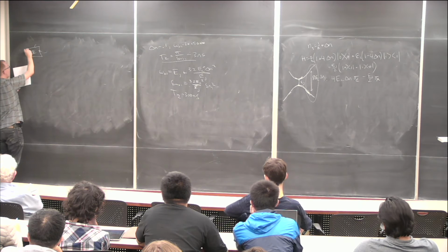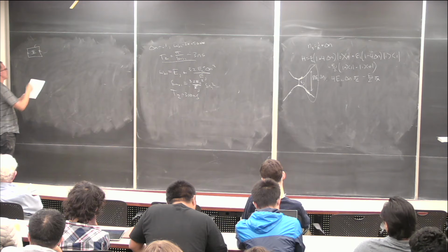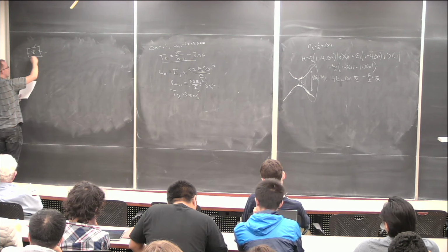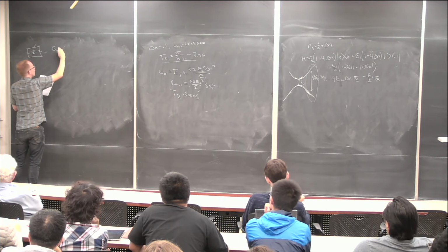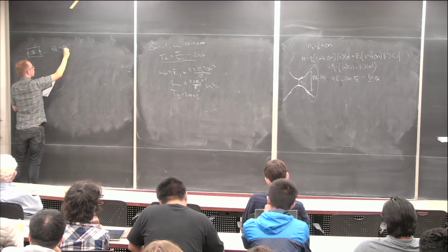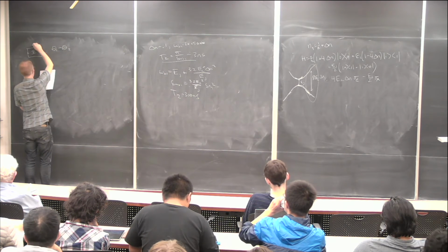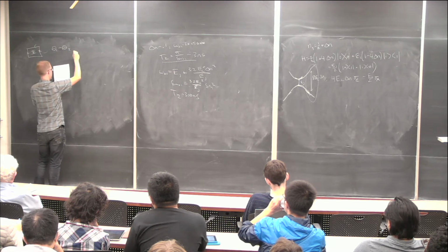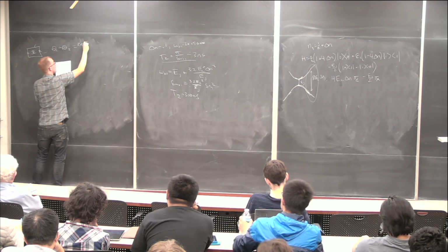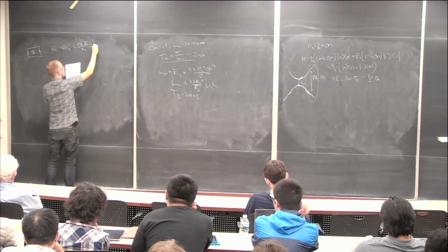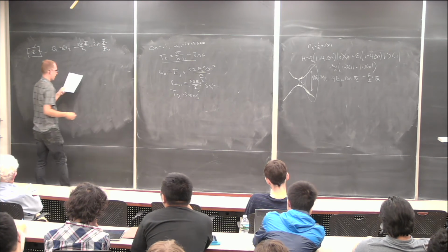And so as you go around the loop, then you need to have the phase well-defined, right? So if I start here and I work my way around the loop, then I need to have all of the phases work out so that I don't have sort of doubly defined phase. So theta 1 minus theta 2, if that's the superconducting phase up here and down there, has to equal 2e phi over h bar, or 2 pi phi over phi naught. Phi naught is our flux quantum.